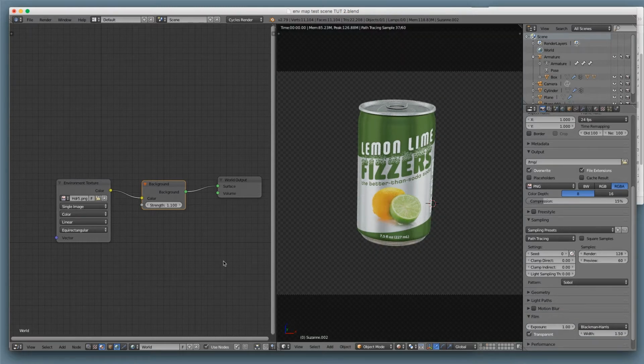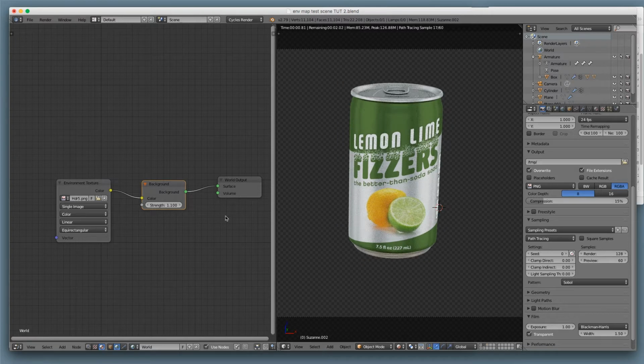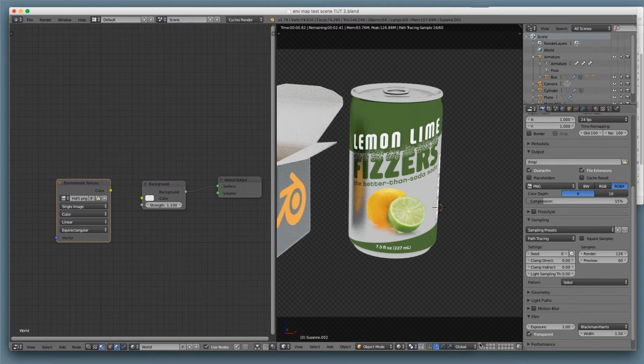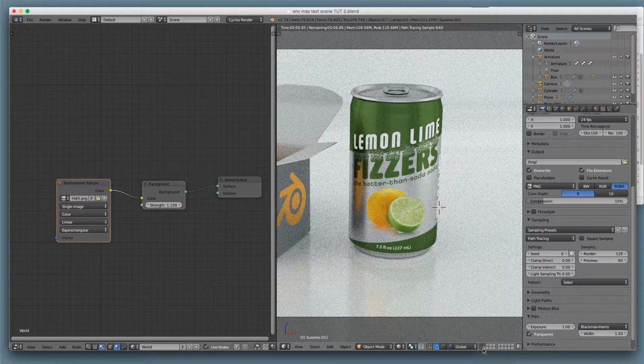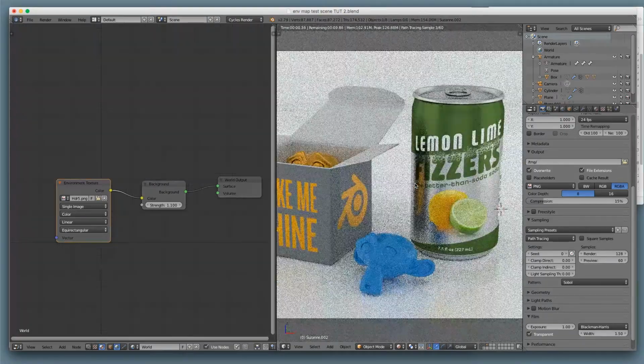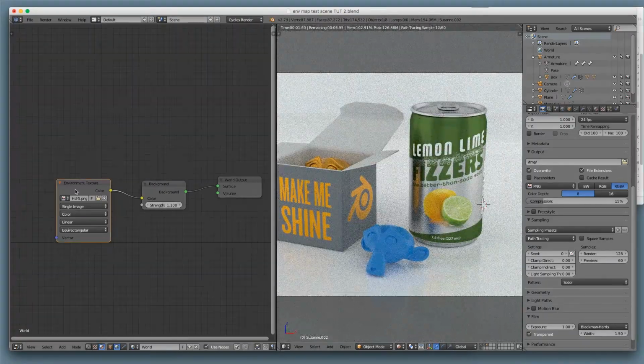So we don't see any of the background, but even then, you can see this does not look metallic, whereas this does, because it has something to reflect. Obviously, I can make it look a little bit more metallic if we give that something to reflect, but it really just helps to have an environment map, and then we can have the sky and a whole bunch of other fun stuff in there too. And we can bring Suzanne back here. So that's the why of the environment map.